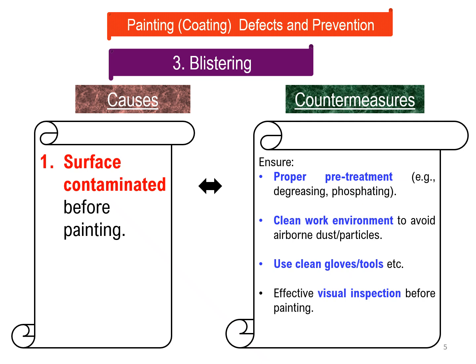Number two, clean work environment to avoid airborne dust particles. Number three, use clean gloves and other tools, etc. Number four, effective visual inspection before painting.